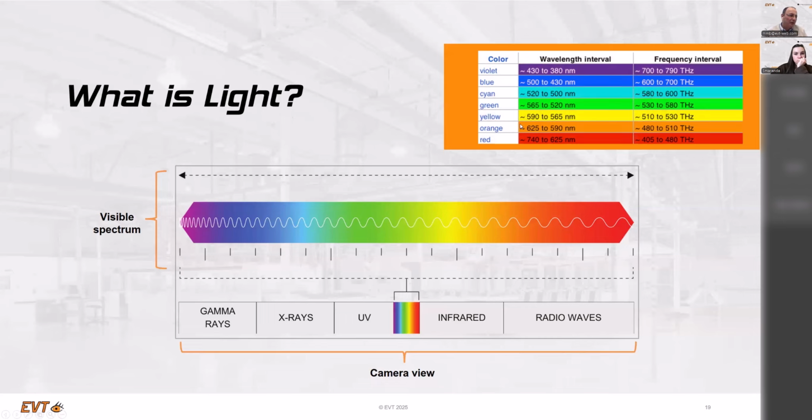Therefore, we have a short overview about the different light sources. And as I said before, if you only have to decide whether the part is red or green or yellow, you could use a gray camera and select a fitting color light source, because you can generate the opposite reaction of your target color.